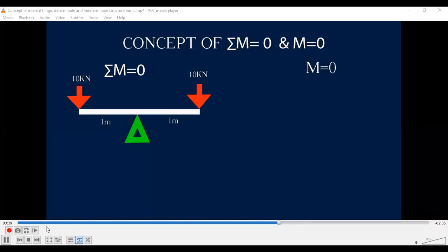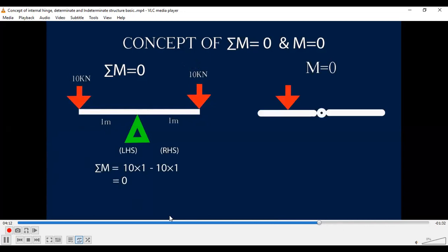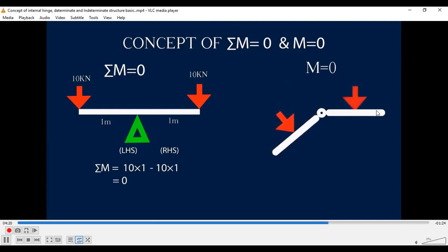So you can see if you apply a continuous beam, the beam is always straight, right? So here, the relative rotation, right? Compared to the right-hand side part, how much has it relatively moved? You know, it is in the same straight line, right? So that means the relative rotation is still zero if it is continuous. But if you provide a hinge so that it can move relatively, can you see there's a relative rotation? It is no longer in the same line, right? So there's a relative rotation, right?